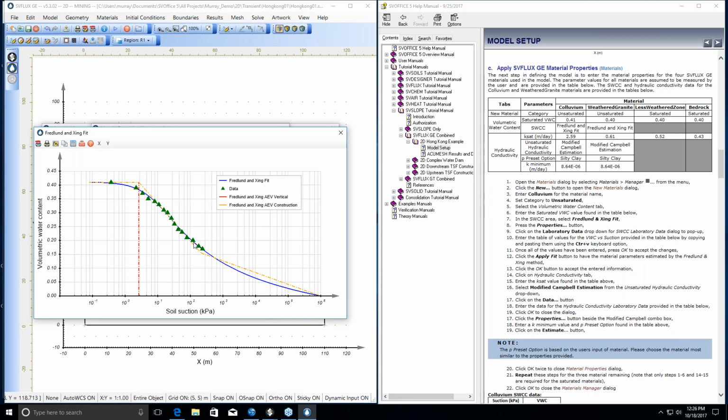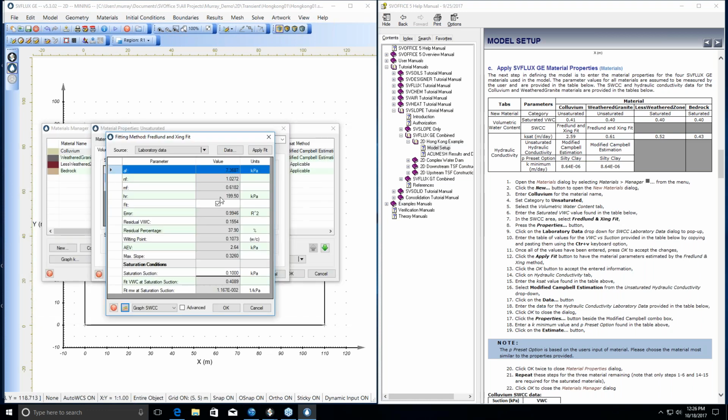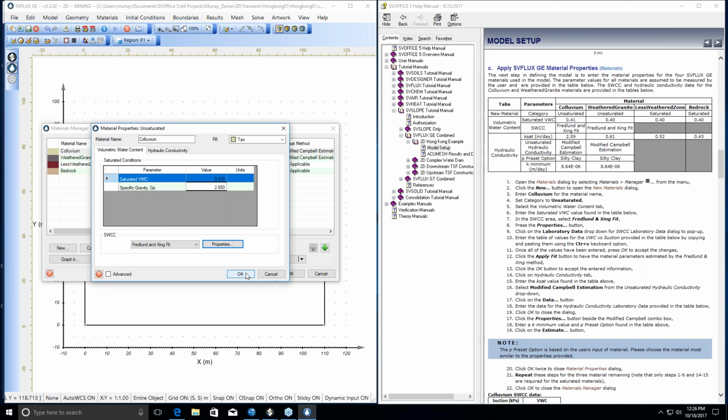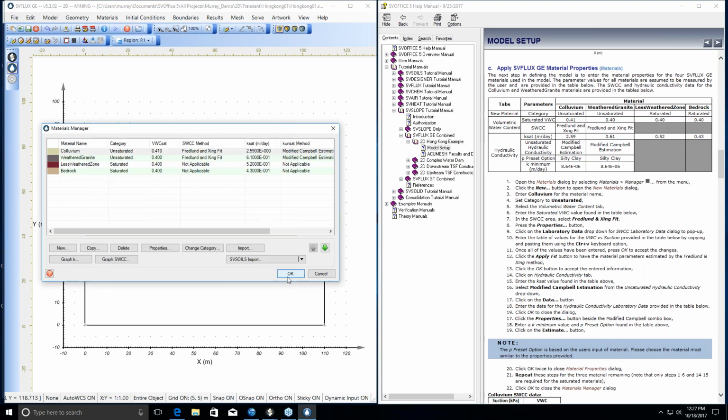And then the rate of change slows out through here, as you're able to pull less water from the smaller pores. So the air entry value and just afterwards is typically the zone of largest desaturation. In other words, the larger pores are emptying in the soil. So hopefully that explains what that is. It's more just a representative of how fast the water is able to be taken out of the soil after the air entry value is exceeded.